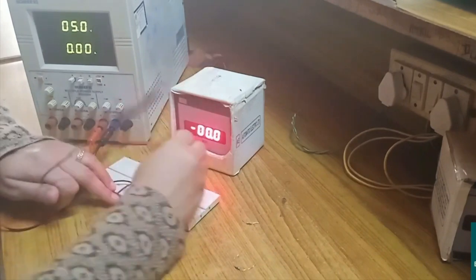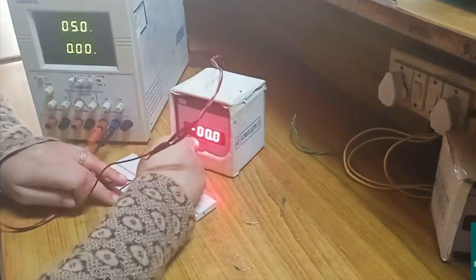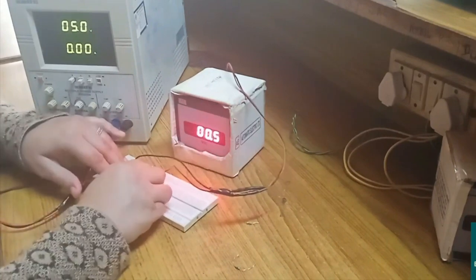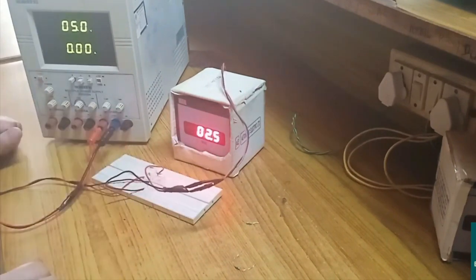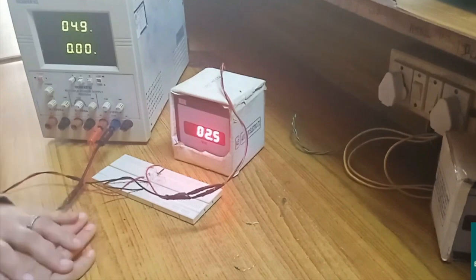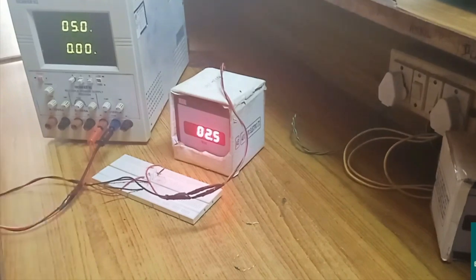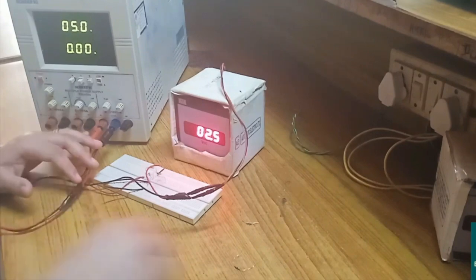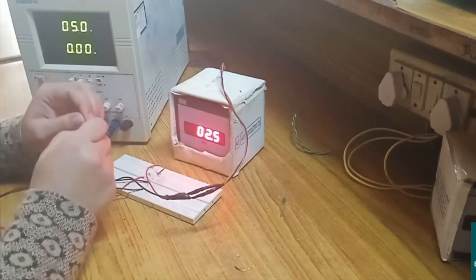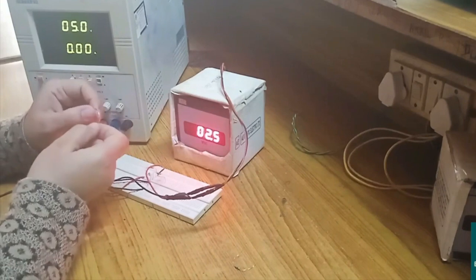So how will the connections be? The positive of the voltmeter is connected with the first terminal of this 220 ohm resistance, whereas the negative is connected with the other terminal. That is the parallel connection. So now you can have a look. VTH comes out to be equal to 2.5 volt. This is VTH. Step number 3 is the calculation of RTH, and it will be done manually. RTH comes out to be equal to 330 ohm. So what will be the color coding for RTH? So this is your RTH, orange, orange and brown. This is the color coding for RTH, 330 ohm.